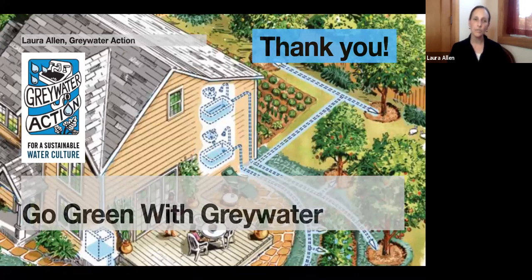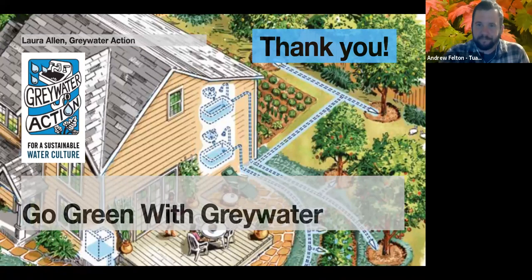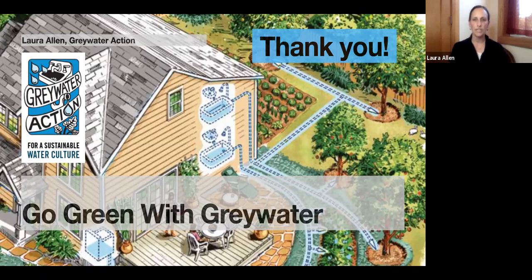So going to the septic question, that is an important question. If the septic system is a standard septic tank and leach field, when you remove the Greywater, you're increasing the retention time in the septic tank, which actually helps with treatment. So if your septic tank is properly functioning, and there's not some other issue going on, removing Greywater increases retention time in the tank. That actually can have a benefit to the treatment. And there are studies that show that.